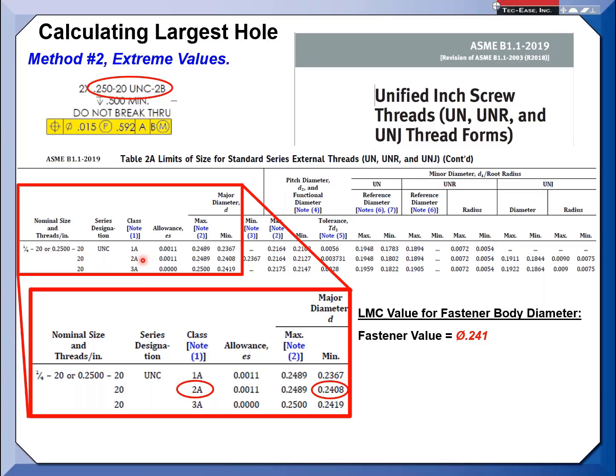I personally like M on threads because I can build a hard gauge to check that when you have M's. If I don't have the M on there, I have to have an expanding gauge element that would hit on the pitch diameter of the thread. And I've done that too. I've had flight critical hardware, keeping things flying in the air.